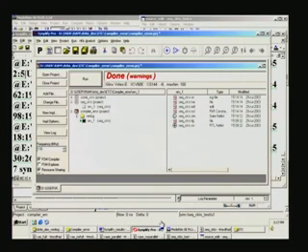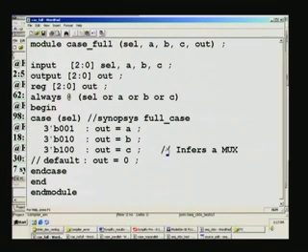So, next we will move on, we have been dealing with RTL coding guidelines. We have covered Synopsys full case, then Synopsys parallel case, etc. We will take up those files independently and see how the optimization really works, right. Let us have a look first at the source code for the full case. This is called the full case here,